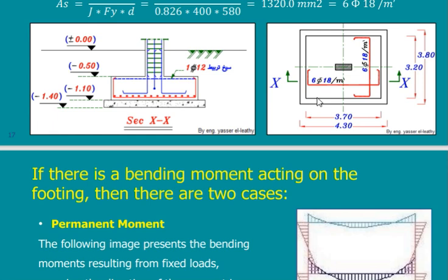Either on the drawing you write 5 rebars per meter, or you write 20 rebars from edge to edge, like what you do in beams. In a beam, you don't write the reinforcement per meter, because the width of the beam is 30 centimeters or something. So you just put the full amount.